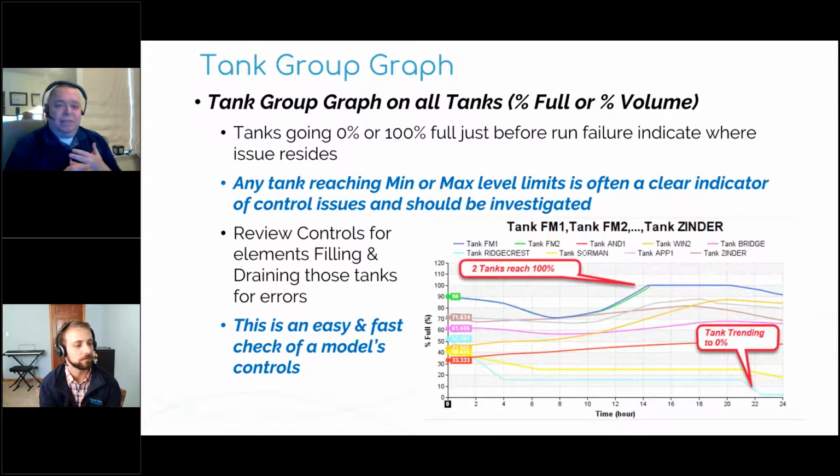Most of the time when I see a model that crashes midway through a run, it's almost 90% of the time a tank that ran out of water or filled up just before the crash. And so you can say, okay, if you've got a system schematic or a hydraulic profile, these elements fill this tank. Okay, let's look at those controls. That's very helpful to troubleshoot.